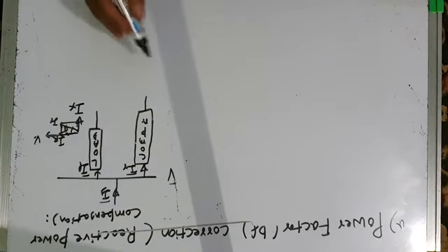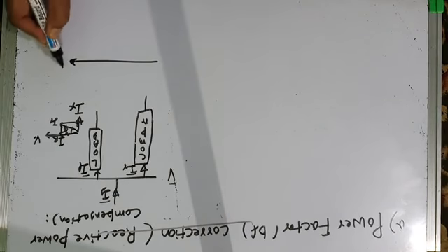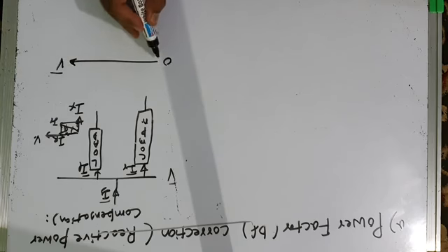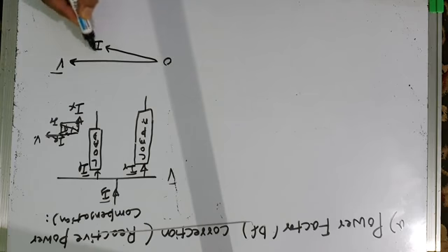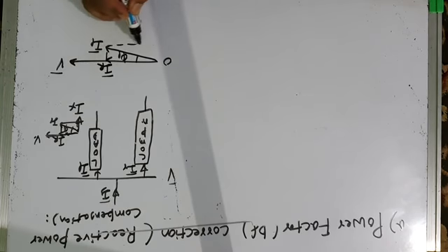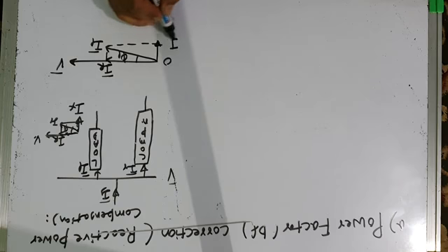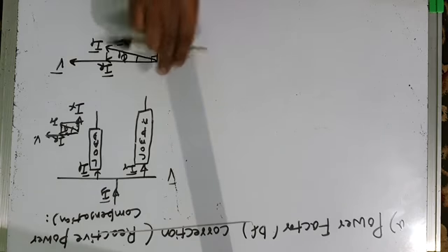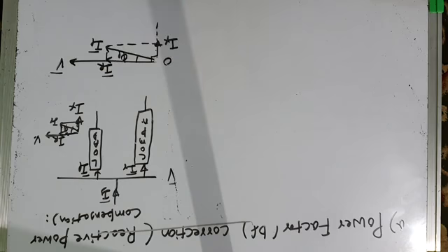If you draw the phasor diagram for this situation, this is the voltage phasor V. This is current IL which lags behind voltage by phi L. This is the resistive component or in phase component of current IR, and this is the reactive component of current Ix, and we want to cancel this reactive component of current, because you can see it is this reactive or quadrature component of current which causes IL to be displaced with respect to voltage. It causes IL to lag behind the voltage by phase angle phi L and causes power factor equal to cos phi L, which is less than unity.